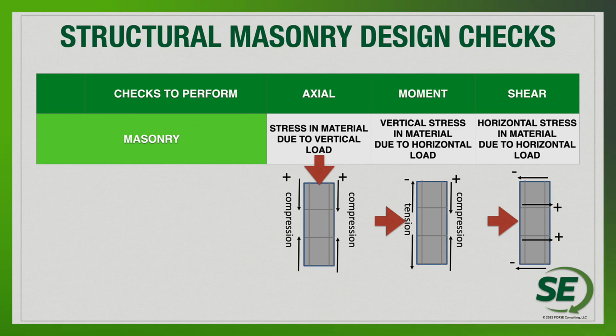Again, bringing this back into our table, looking at the different masonry elements that we might want to look at. Axial forces: anytime we have an element where the primary forces are going to be axial, we know that the masonry material is going to do pretty well in those applications. Anytime that we do have moment and shear, where we have lateral forces, we know that we have some tension and compression that's going to be created, so we know we maybe have to move into reinforced masonry elements to gain the full capacity that we are looking at for that design.